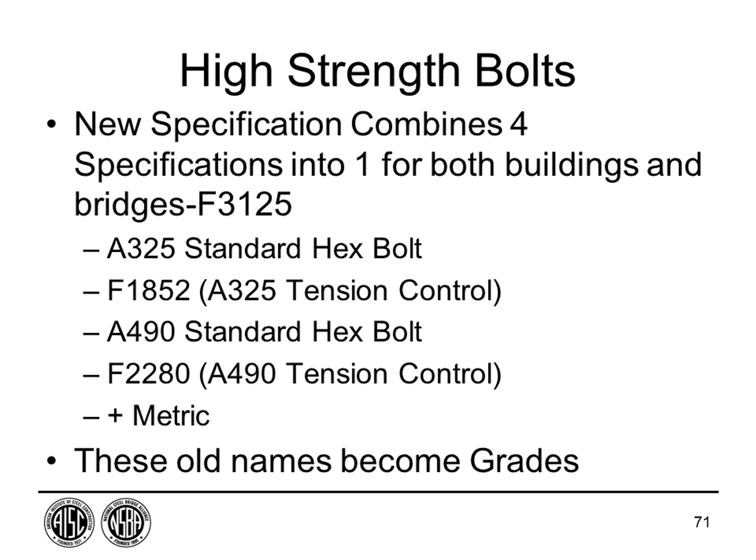And then also, we have a question about specifying what used to be A325 bolts. So now the grade is A325. That's correct. And this person would like your recommendation on whether this necessitates a change in how this is referenced in plans and details and notes as well. Yeah, I would think you have to say F3125 grade A325 would be the proper way. It's a little bit like specifying A709 grade 50W. It would be similar.